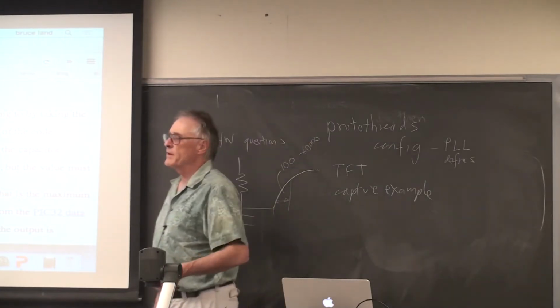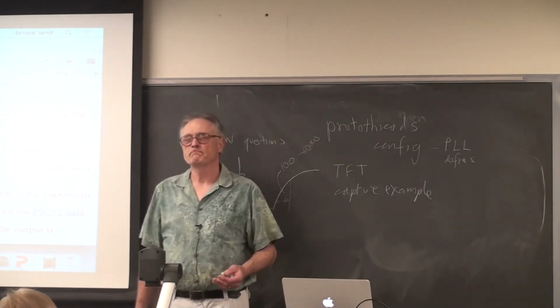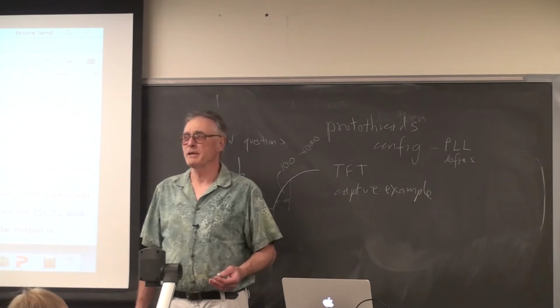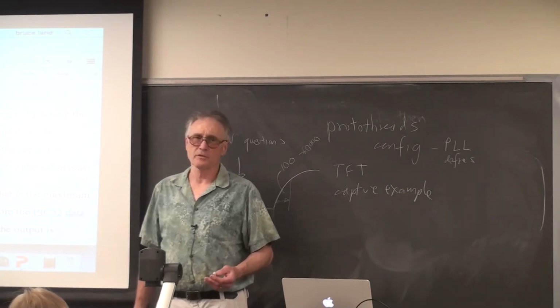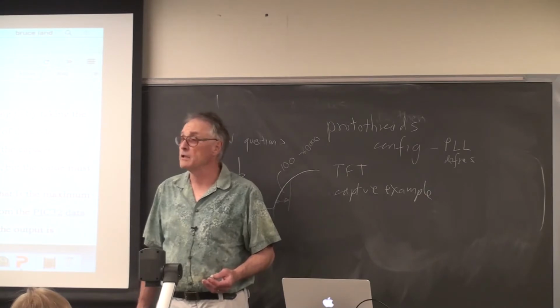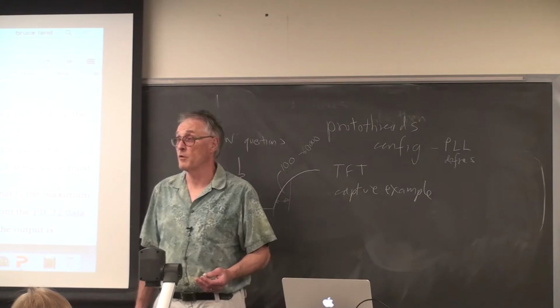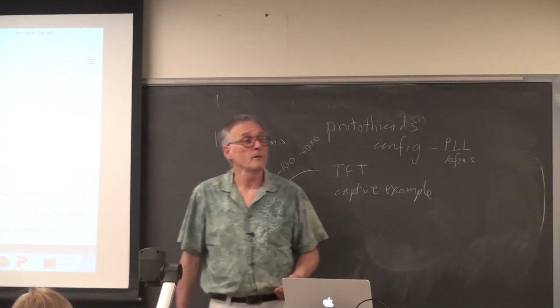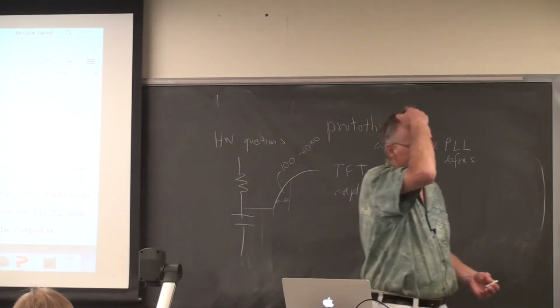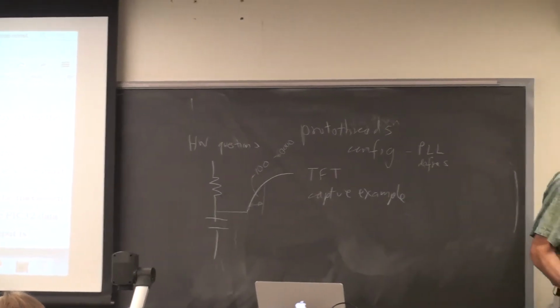So our group today had a value of 10 to the 11th ohms. My fingerprint on a piece of glass is about 10 to the 9th ohms. So you can guess that 10 to the 11th ohms is hard to come by. It can be done if you wash the board, if you guard the board and wash it with isopropanol. But that's an unreasonably big value.